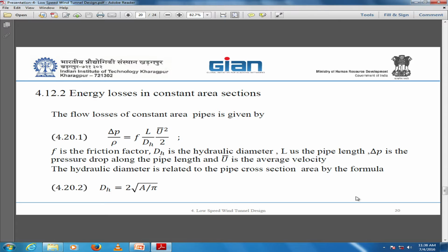So the length of the contact area times the shear stress times the circumference is actually the envelope of that contact times the shear stress. This is one force. On the other side, the pressure is working on the cross-section area, which is A_CA times delta p. And for a circular pipe, you can express the shear stress as that formula, 4 times tau. It's one quarter f times dynamic pressure.